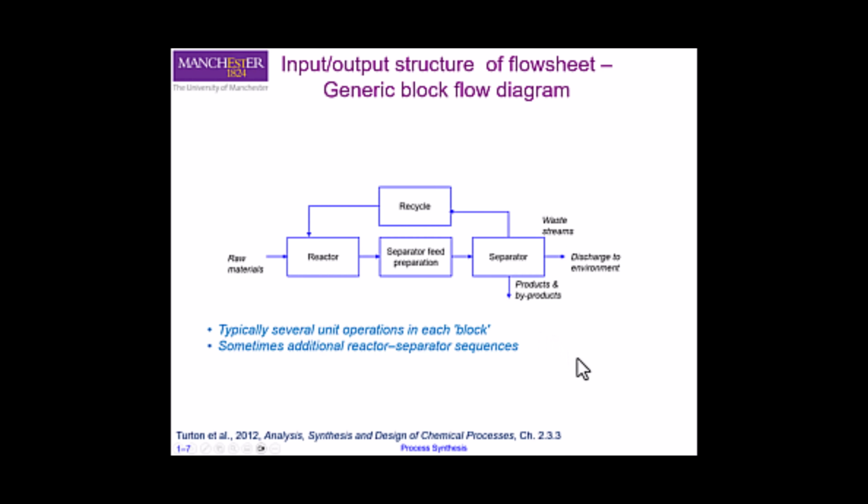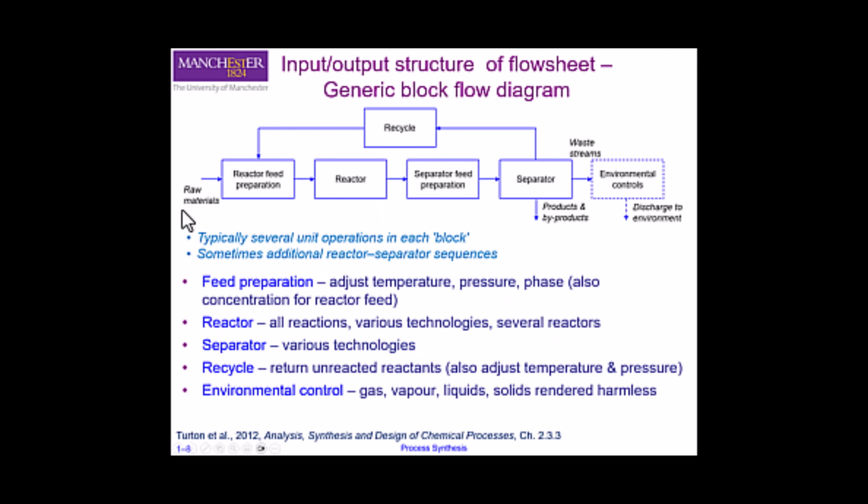Okay, so this is a very basic structure here. But depending on your system, you might want to add more details. For example, you might want to add a feed preparation step because you might have to raise the temperature, pressure, or change the phase of your reactants before you feed into the reactor. The reactor itself can be a series of reactors or can be different technologies. Similarly, there are various technologies available for separation: distillation, membranes, absorption.